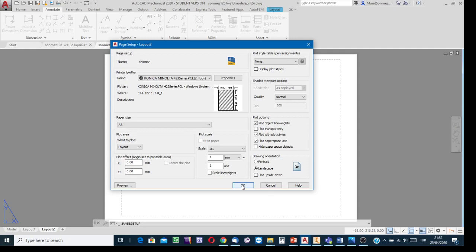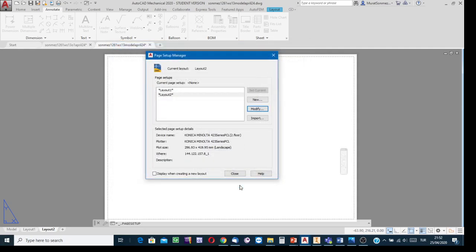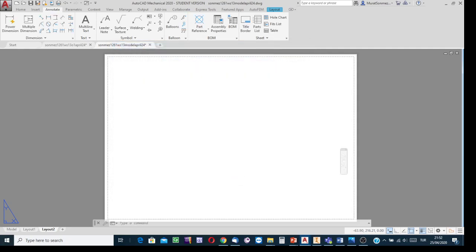But in Inventor, selecting the British unit system can guarantee to have the papers in standard size in accordance with ANSI. In the next video record you're going to see how. But here, plotting scale is 1 to 1 and say okay. And then close this dialog box.